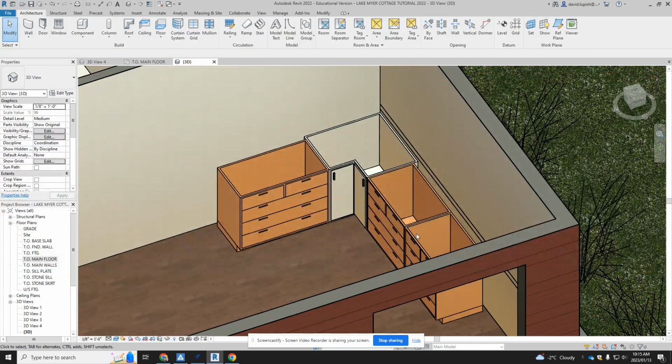It's going to eliminate having to deal with the change in the colors and all that. Maybe you like the variation in colors. So I now have the top of my cabinetry all consistent at 2'10.5" in height. And because it's sitting on top of a 3/4 inch hardwood, I actually have a distance from my level to the top of my cabinets of 2'11.25".